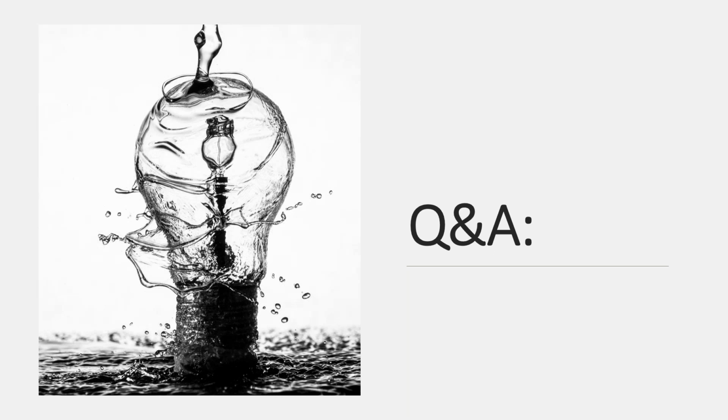Okay, so another one here. This is also answered by Will. The question is, with regards to the chart on slide 19, do I understand this correctly? If someone were to ask for malleable fittings rated for 300 psi, it could be a class 150 fitting? The answer is exactly. A class 150 fitting is rated for 300 psi as long as the operating temperature does not exceed 150 degrees Fahrenheit.